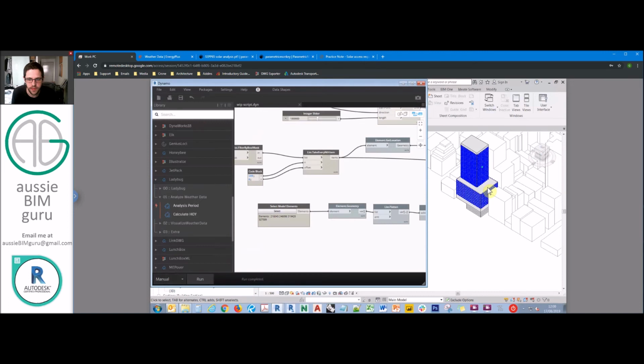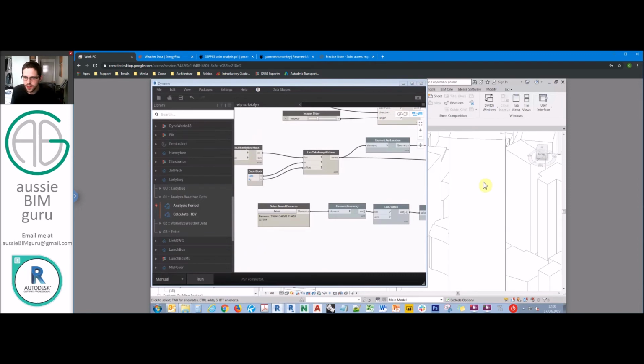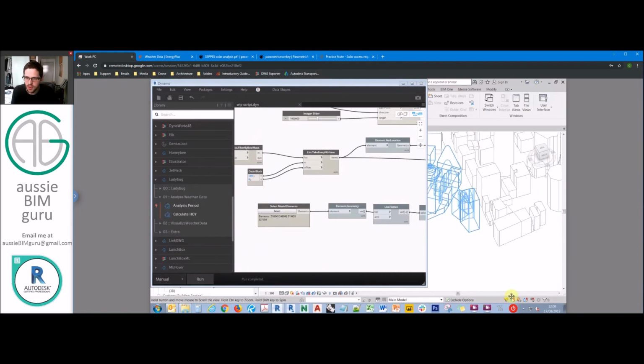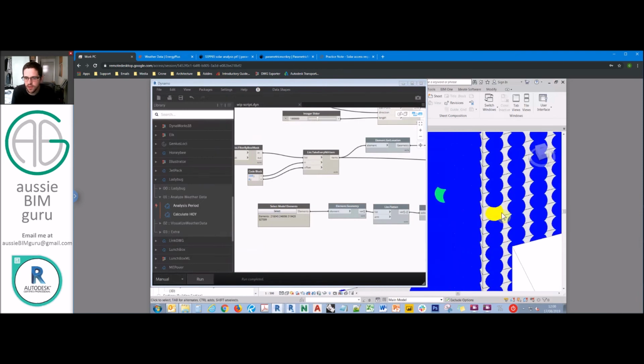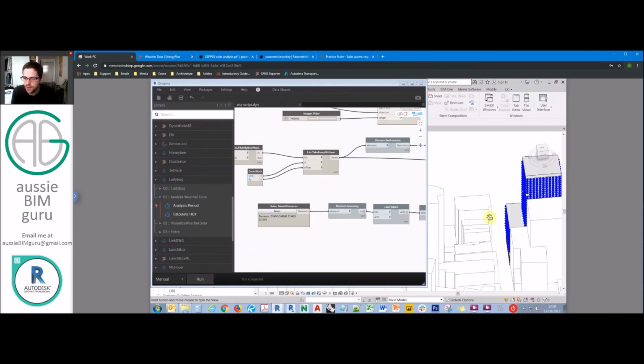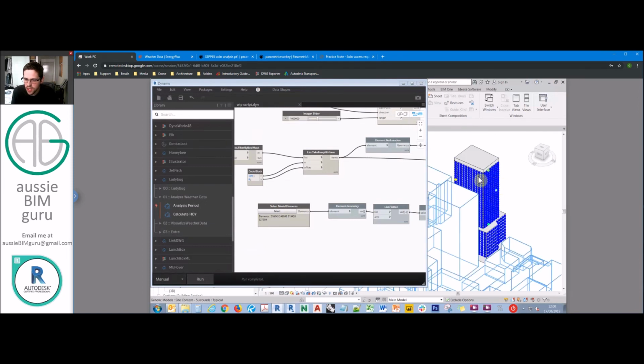And there they are. So you can see one's here. This sensor now receives, I think, 4 hours, which that color represents. But there'll be other ones too that have more sun. So you expect the ones on the front face of the building will receive quite a lot of sun. So you can see that one there receives 7 full hours of sun. So it's really easy to visualize just how our building is performing.